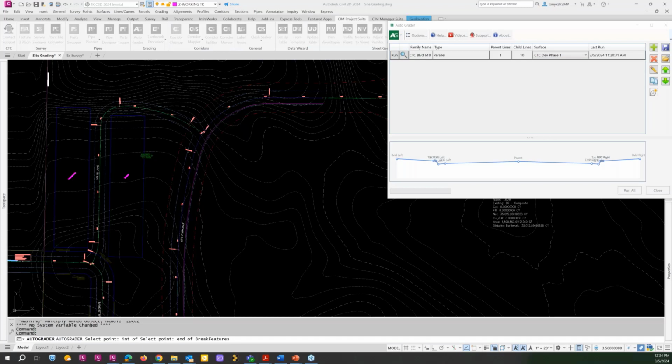And with that, I see a question came in. The question is, you said by default the table goes to the center of the drawing. What are some other options for table location? Is there a way to set that default location instead of being centralized? There is not. However, if you do move it like I did there, the next time it comes in, it will land in the same spot. My table style or my text style wasn't the proper one for coming out in paper space, so it came tiny like that. But again, it's just an AutoCAD entity. So we can do whatever we want with it.